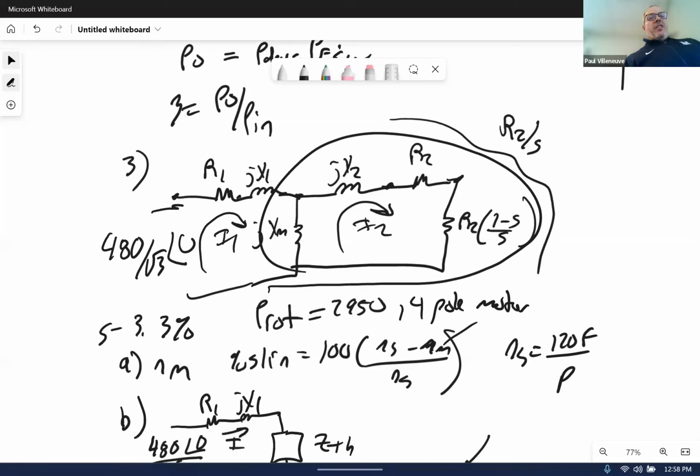If I know the voltage and the current, isn't Z Thevenin equal to V Thevenin divided by I Norton? You solve for current using whatever nodal analysis technique you want, and then you just solve for Z. Very basic. So they're not sitting there doing combinations and turning power supplies off and doing all this stuff. They're just like, I'll just calculate what the current is. Once I know the voltage and I've got the current, I'll give you Z. There's no guesswork, essentially.